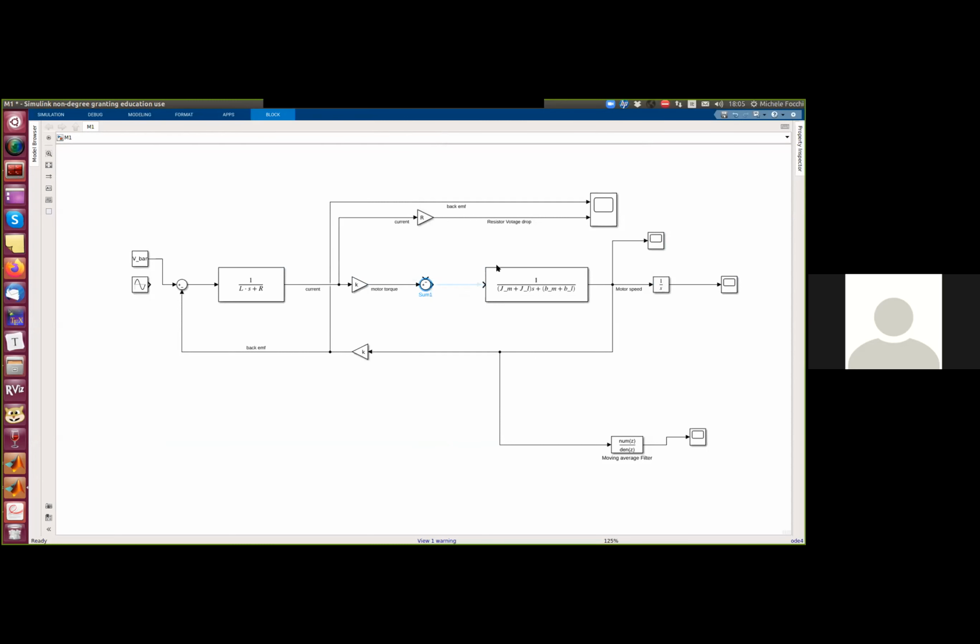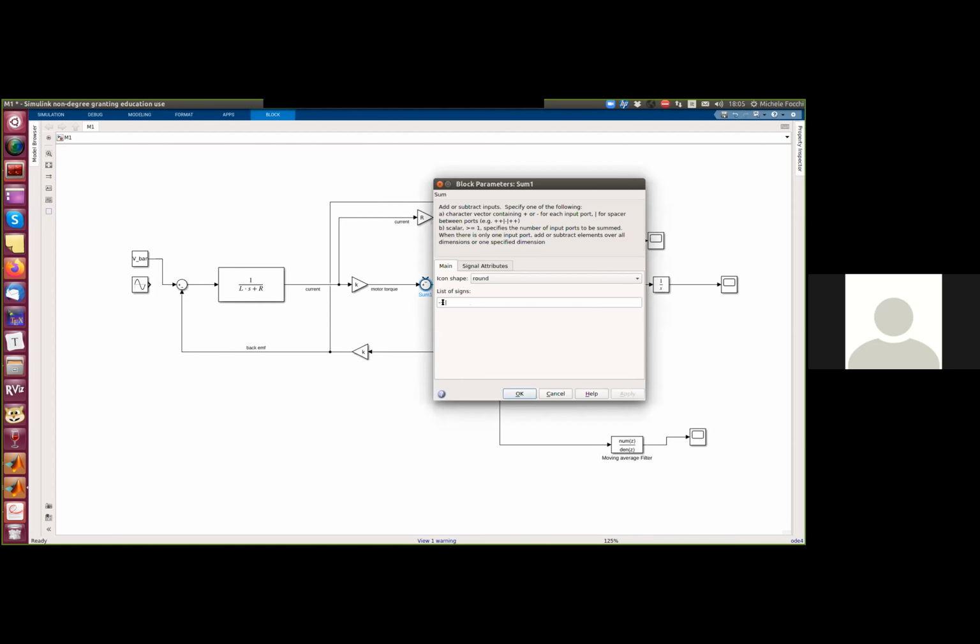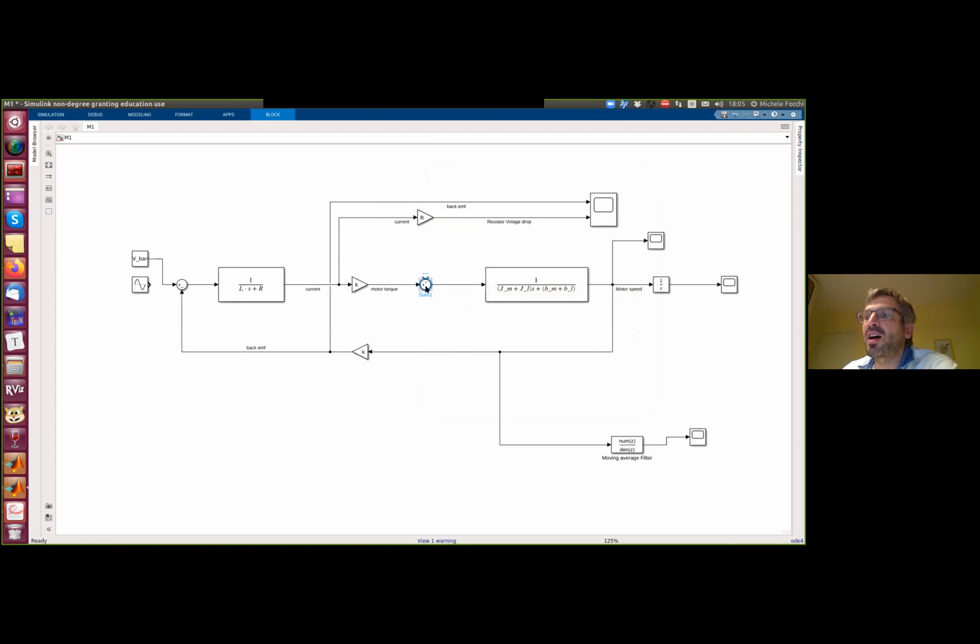Maybe you should explain what you did in the block. So now we are trying to add a load torque. The load torque is subtracted from the tau amp. If you remember the slides, the motor torque. What I mean is what you did in the block, because you did it a bit fast, to rearrange the signs. This is to rearrange just the plus and minus in the summing, and then with Control R you can rotate it.